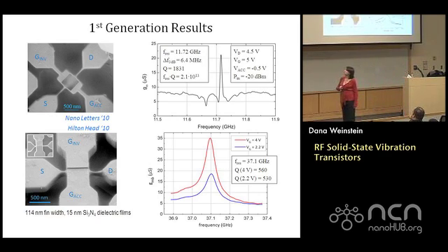And these were the first generation devices that we used to demonstrate this structure. These were built in-house. And what you see here is that same structure, gates, source, drain, and it's expanding and contracting in this direction. And we demonstrated up to 37 gigahertz acoustic resonance with frequency quality factor products comparable to those at lower frequency. So actually still among the highest in silicon to that date. And this was about an order of magnitude higher frequency than ever done before.